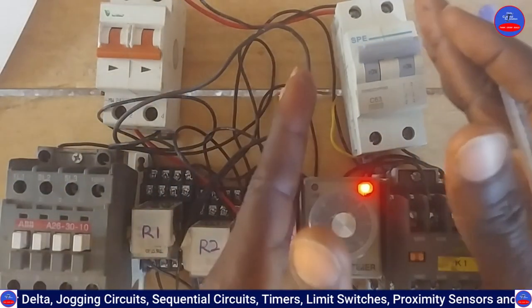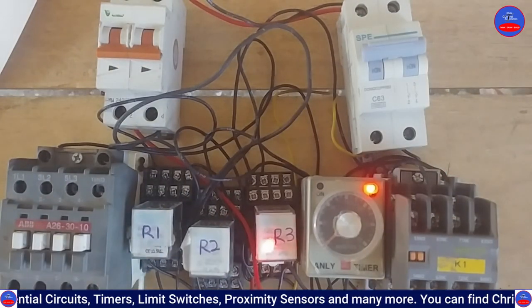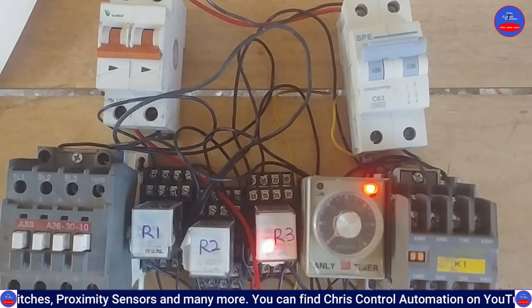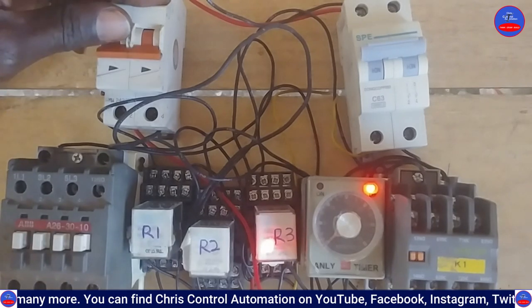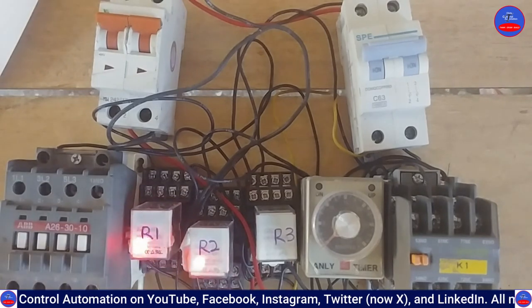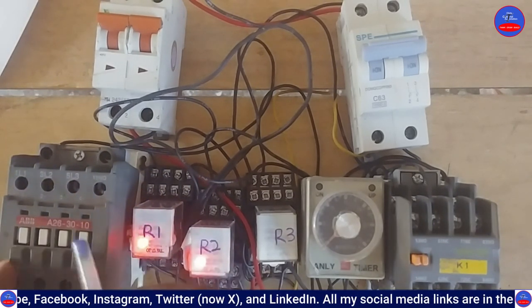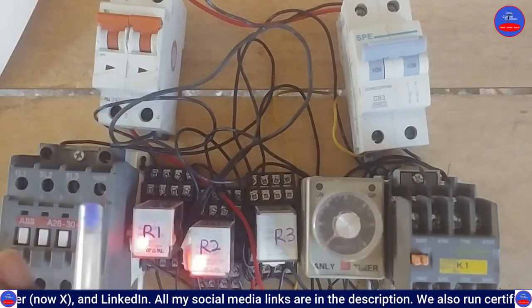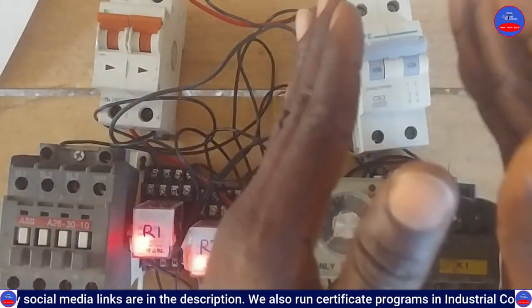So let's see what happens here. When the genset is running and then the utility power comes in, let's see, it is restored. All right, let's switch on the breaker. You see that the utility contactor is immediately energized and the power is there. Though in the next circuit you are going to add another timer, for now our focus is on the generator side.